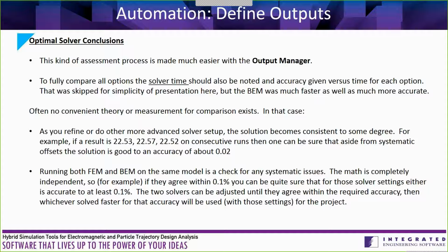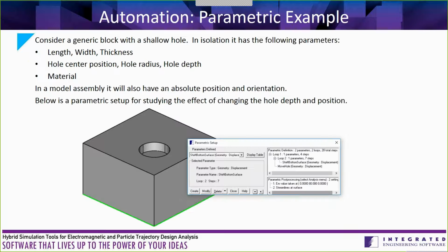For this particular type of study, just a piece of advice: what you really want to do is compare solver time. You don't want to just look at settings, because for all you know, my best case took a lot longer than my poorer case. So it's really solver time you want to be focusing on. I should also mention solver time plus interaction time.